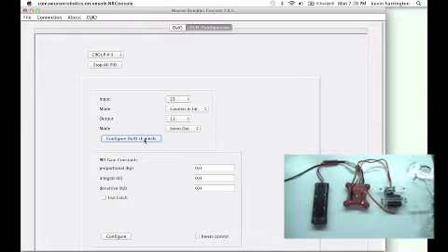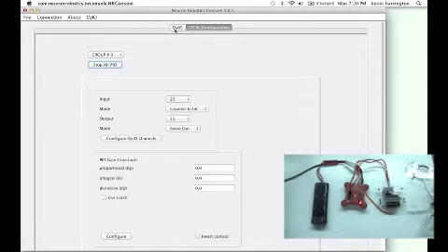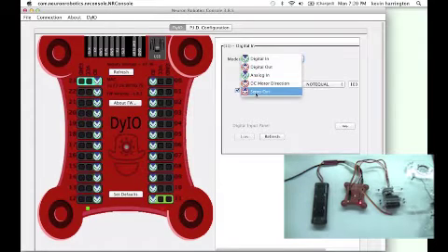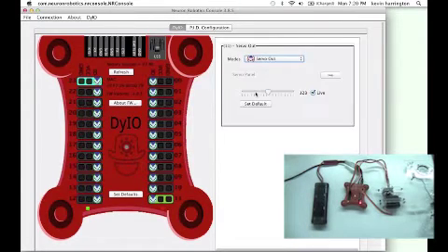If you start your PID controller and notice your motor begins moving immediately, you can first of all stop all PID controllers, go back to the DyIO panel, and make a configuration to this channel.